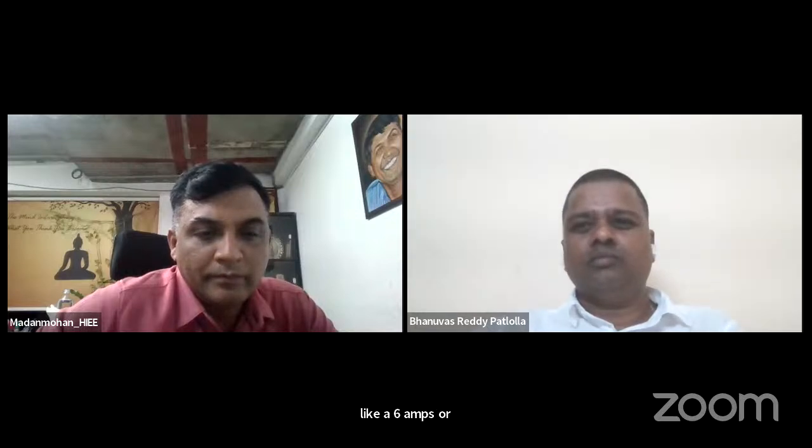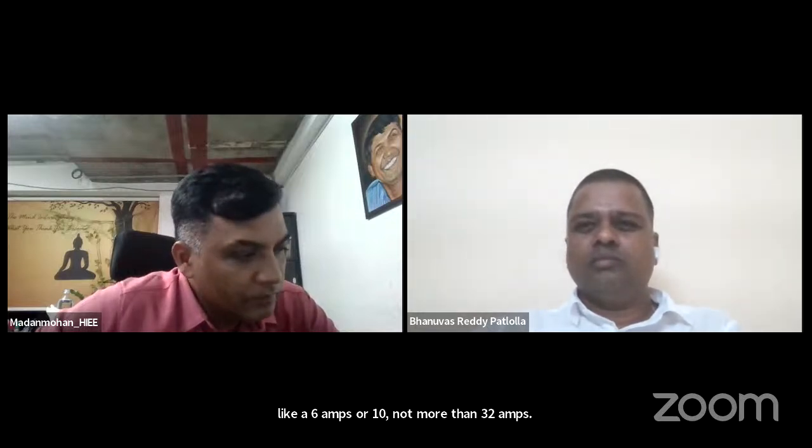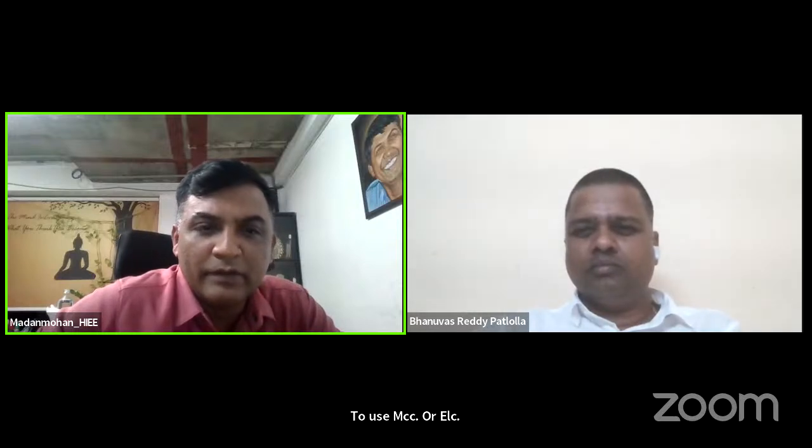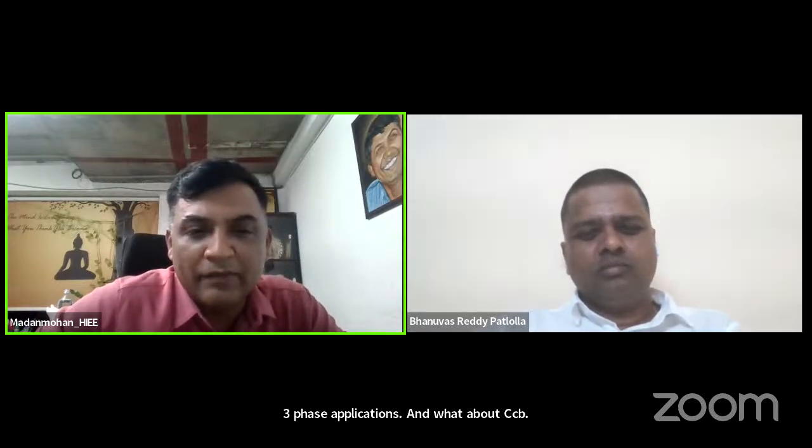But sir, is there any restriction of load to use MCCB or ELCB? Especially, you don't have MCCBs for single phase applications. MCCBs are generally preferred for three-phase applications. And what about ELCB? MCBs are available for three phase and single phase. No, I'm talking about ELCB.